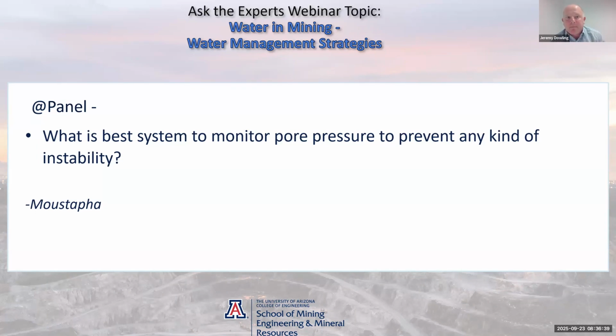Whereas if the concern is more rock mass shearing and deeper seated rock mass failures, then placing most of the monitoring, and the vibrating wire sensors, into the general rock mass, perhaps closer down to the toe, where rock mass shearing may initiate, would be the best thing to do in that circumstance, right?